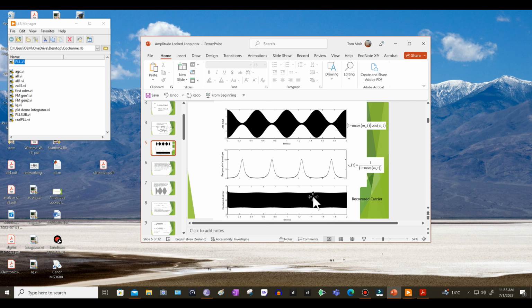And then actually we went on to demodulate double sideband suppressed carrier, which is almost the same as AM, but you haven't got the 1 part in there. You just multiply these two, so there's no power at the carrier, and we managed to make that work quite well actually, because what happened was we got rid of the hard limiter that's usually used in a phase lock loop, and we put an amplitude lock loop in there instead.